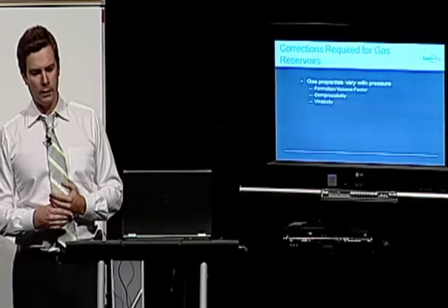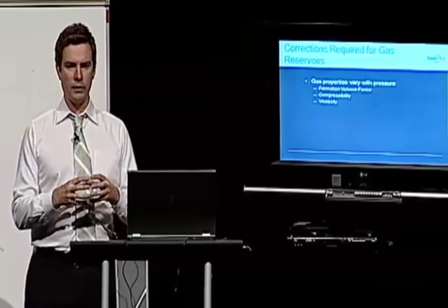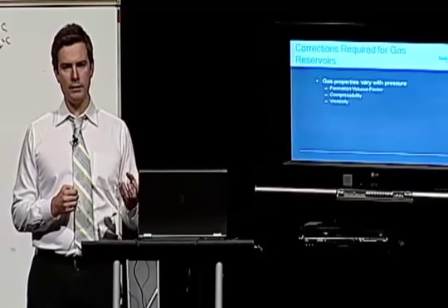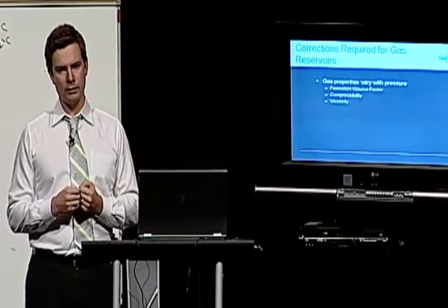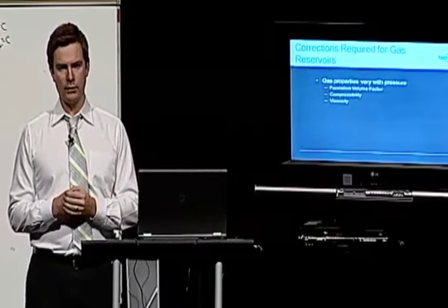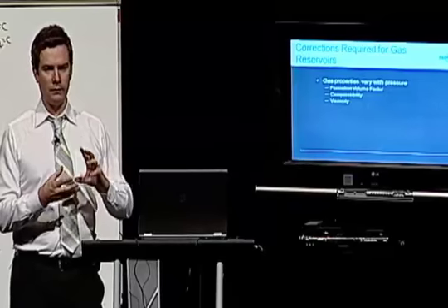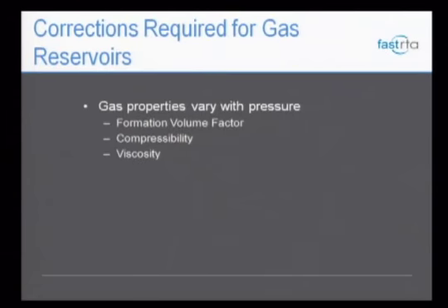Most important thing to remember when we're talking about gas properties as opposed to oil properties is that gas properties are going to vary significantly with pressure. And gas compressibility is much, much higher than oil compressibility or liquid compressibility in general. Okay? A gas basically expands to fill its container. And so its properties are significantly different and have a different behavior with pressure and time than oil properties do.